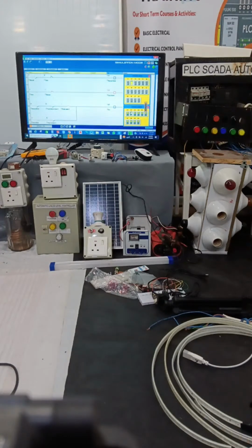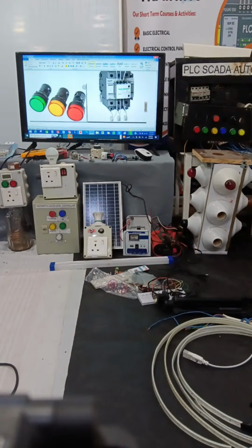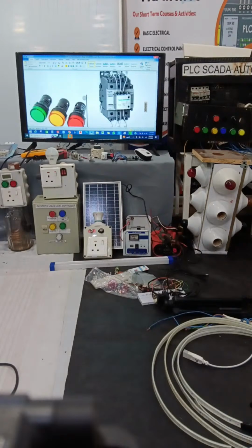Now this is in our diagram. We can see these are the push buttons. When you press this, it is spring operated and will be closed momentarily. This is one NO contactor, and this is an NC contactor. So these are on and off. Then these are the contactors which give power to the capacitors. This is a special duty contactor called the capacitor duty contactor.